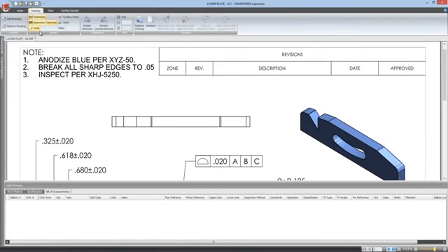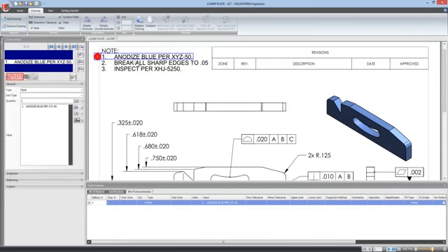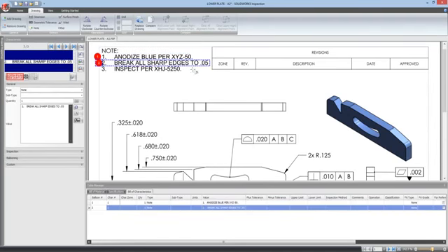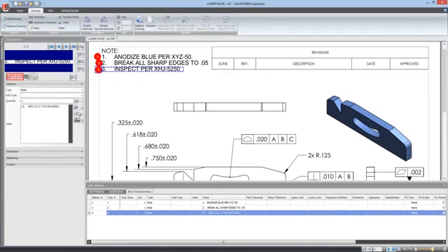drawing, grabbing hold of the things that we want to inspect. So here we're going to want to inspect this note, so again, if we just window round that, that's going to add itself as item 1 to be inspected. We can then maybe select item 2 here and item 3. We might need to redo that one, so you can actually just use the redo facility or move it around or whatever it is you want to do. So we've captured that information now.